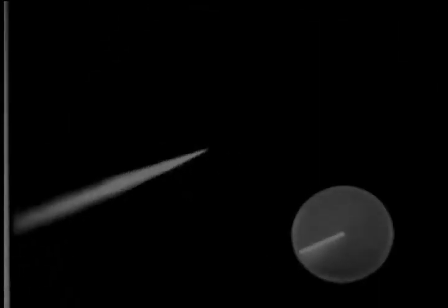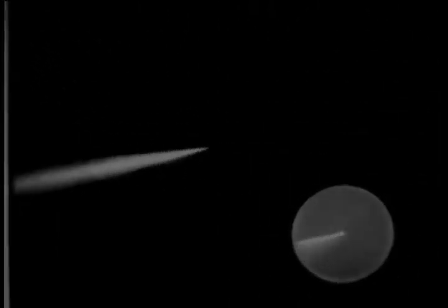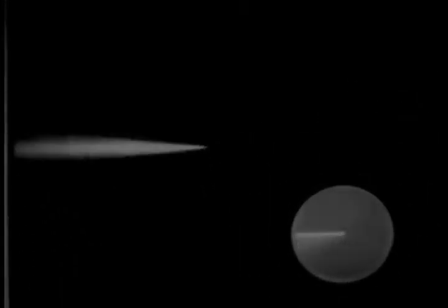Same thing is true of the other set of coils. Current flowing through them one way will deflect the baseline upwards. And a change in polarity will deflect the beam downwards. By synchronizing the flow of current through these coils with the antenna, the baseline will always point in the same direction as the antenna. Thus, by altering the flow of current through the four coils, like this, we can rotate the baseline without rotating the coils, which means we can forget about movable parts, bearings, and the added weight that goes with them. The lightness of this type of PPI makes it very useful for airborne sets.